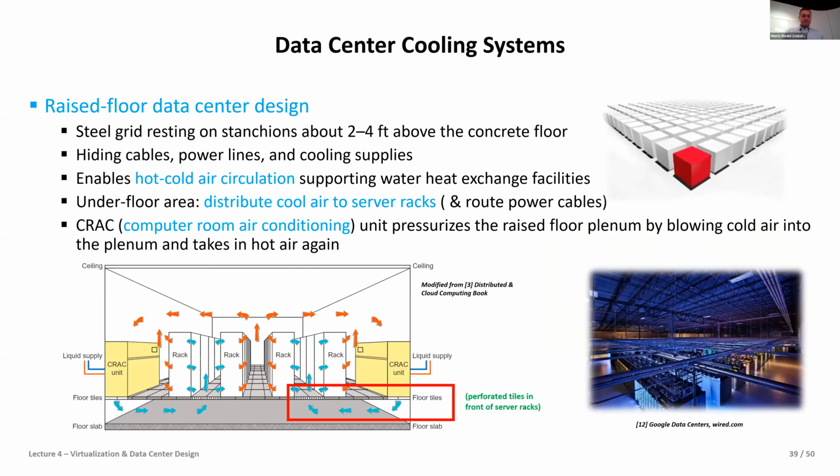Right, so I just talk a little bit about here the idea how this is all fueled and cooled. This was one idea where you see how that works in terms of cooling. You have a second floor and you inject essentially the cold air from the bottom. It will be heated up through the racks, which is all the computers, and then sucked in again. This could be helped with liquid support. So also here, I said water cooling is something you can think about. Today there are very different ways how you can do it, and then use maybe this liquid even for city heating, as I discussed.